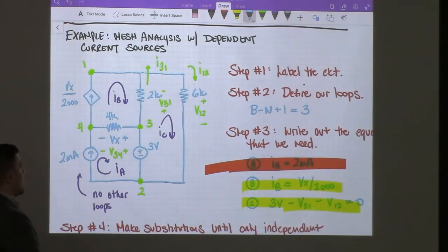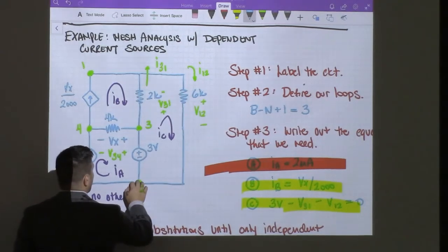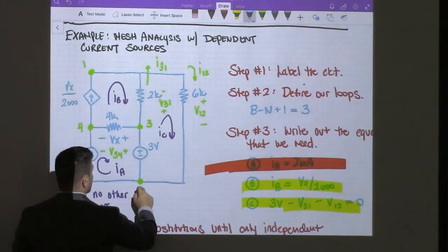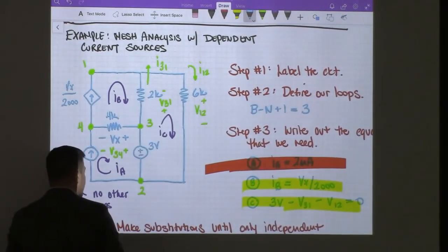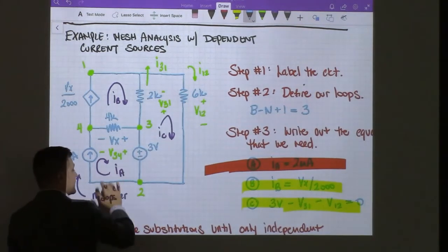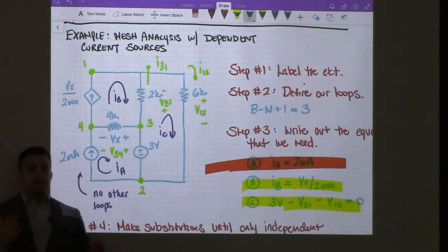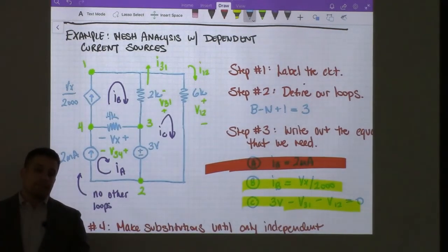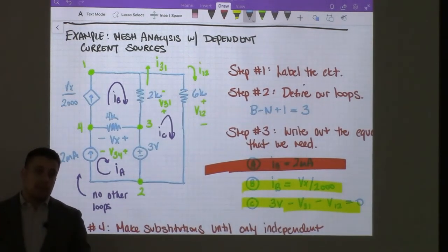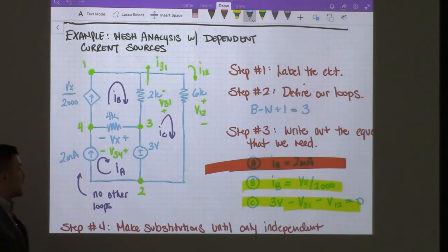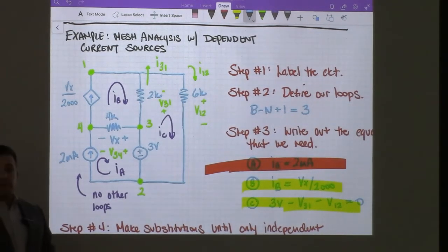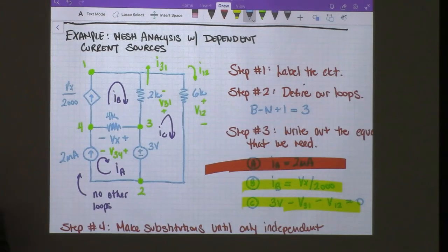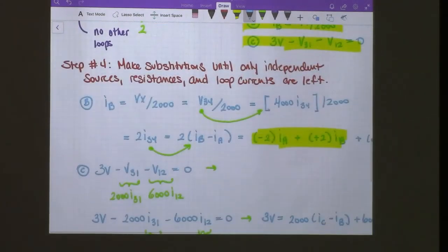If there were a resistance here, then we would have a voltage multiplied by I23, and I23 would be IC minus IA, and that's where it would come into play. But since there's a voltage source there, that relationship is not relevant. So that's the reason why IA doesn't have an effect on that specific part. But it does have an effect on the first loop, right?